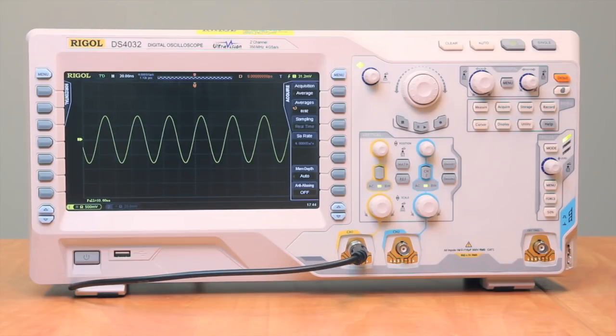Right, so this is a great functionality if you have signals that are repeating, and you want to see the underlying repeating signal and get rid of the noise that's non-systemic, not repeating at that same value. So you can average many of these together, up to thousands really, to get a real clear image of what that would be if there was no asynchronous noise on there.